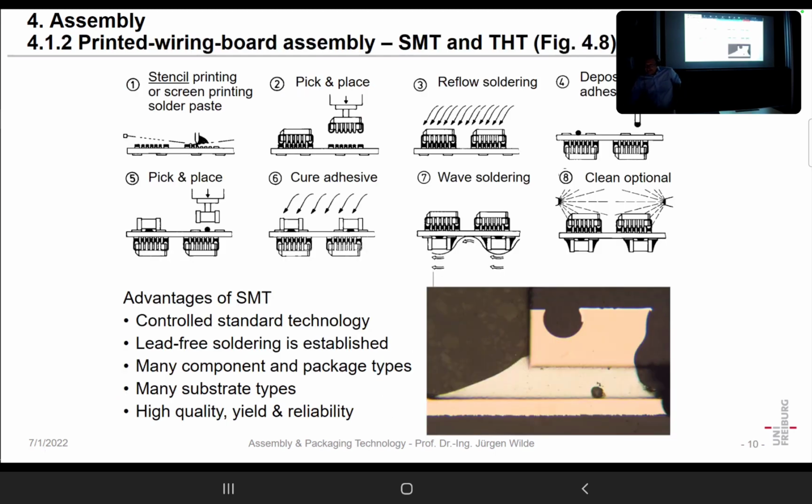You talk about that adhesive material here. I know that's an auxiliary material that is just stable enough to survive all of the process steps. The only reason we have that material is that when we flip that board, the devices will not fall into the solder wave.